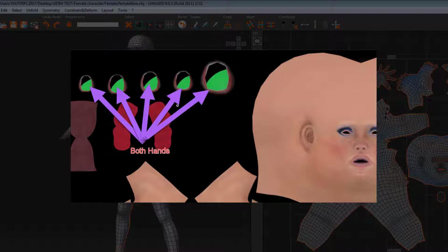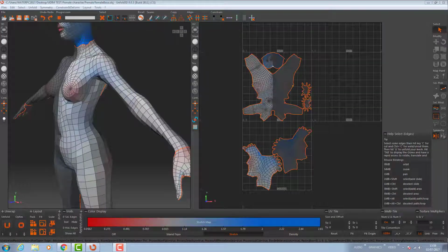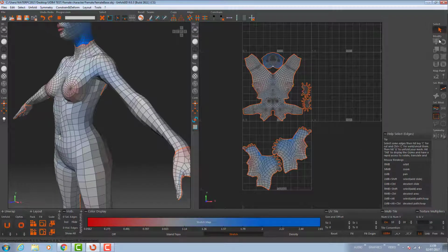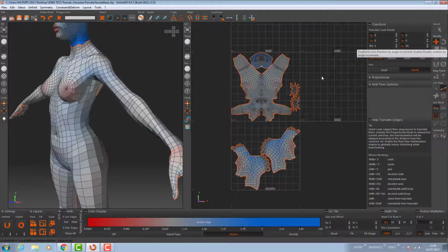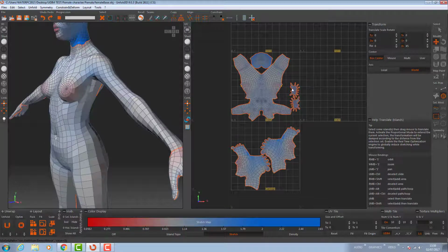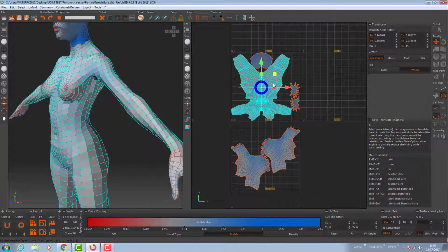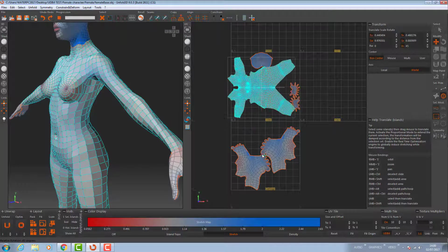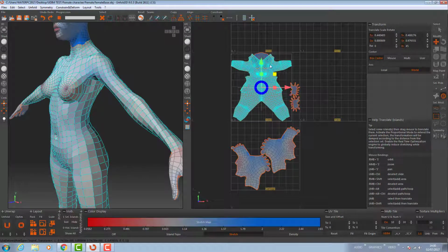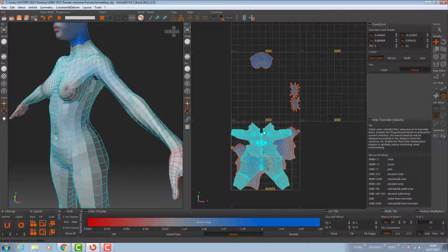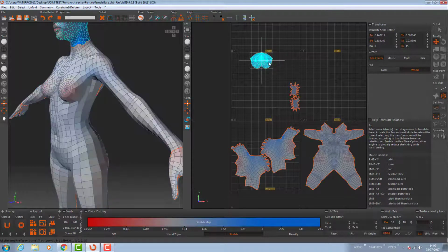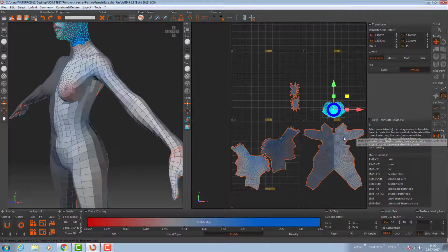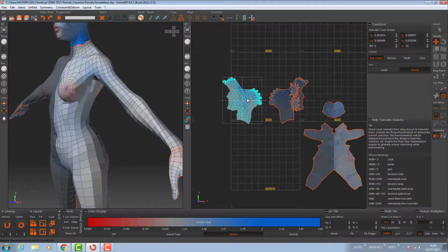Each UV island should remain the same correct scale in relation to each other according to the scale of the 3D model. This is for when you desire the whole model to get equal distribution of quality from the texture map. However, in some cases we may want some areas of the model to have more detail. So we scale the island larger, for instance the head of a character. This could be considered more important at times than the body. The more space an island gets, the more pixels it occupies, which means more detail can be placed on that particular part of the model.